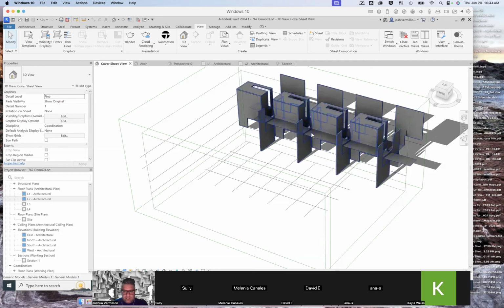And so maybe first of all, I have these vertical structural pieces that can also become walls. Maybe they're bearing walls, or maybe they're just partitions with columns embedded inside. Well, we'll work that out later, right? I'm just thinking out loud, but there's a sort of cadence here along the street edge. Maybe I can put horizontal louvers along this at some point to control light, where I'm not just blocking light, but bouncing light, right? Every time light strikes a surface and bounces, part of the light is converted to heat, and part of the light bounces off and becomes indirect daylight, right?